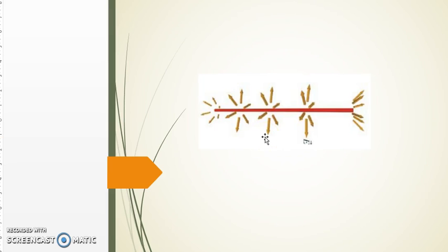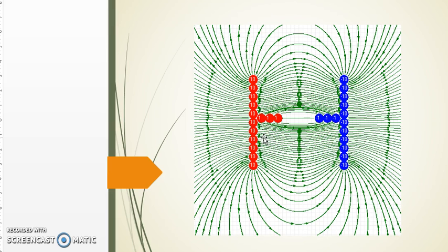So what I did was I went into the eField software and had a go at approximating it. Here's what I've done. Now I'm fully aware that these are not parallel plates here. These are cylindrical rods, so I'm hoping that this will still give a reasonable approximation of the field for a parallel plate, but I'm not 100% sure. Anyway, here I've put a high charge on the two plates, and then to model the thin wires, I've put a low charge on the thin wires and looked at the combined field.